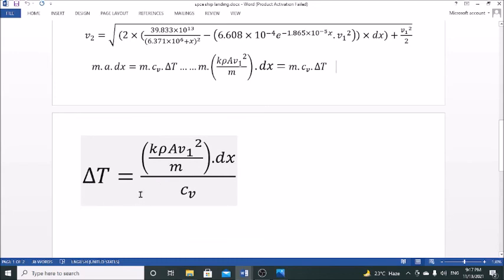Again, delta t, to calculate exactly, I prefer to multiply this quantity by about 0.5, 0.6, because not all the heat generated from friction with air is taken by the spaceship or by the falling body, whatever the falling body is. About 0.6 to 0.5 of this energy is gained by the spaceship, and the other is used to heat up the air.